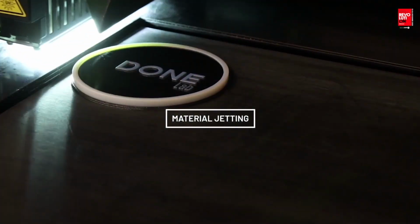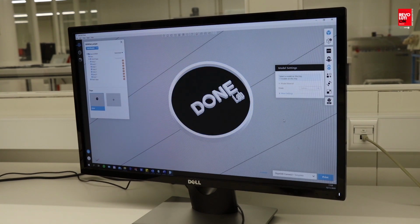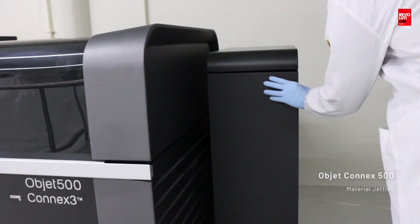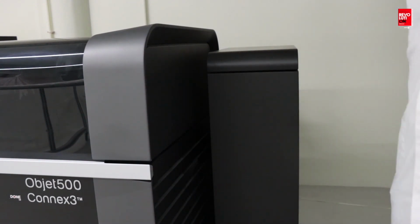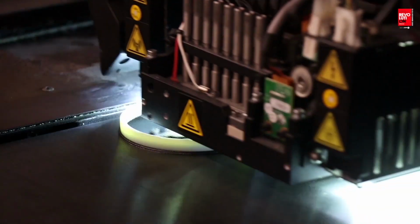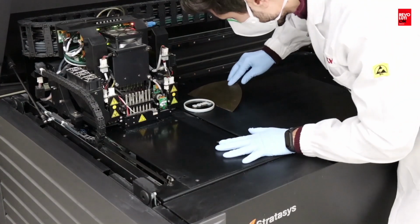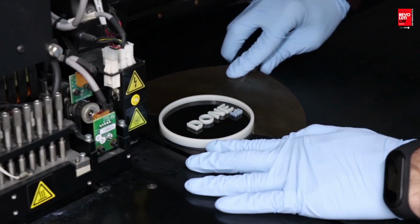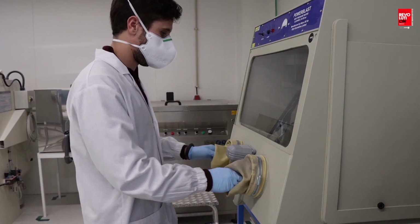Another technology that we have inside the DAN lab is material jetting. The material jetting uses a photosensitive polymer that cures with UV radiation. After we make the data preparation, we put the material inside the machine and this starts the production. In our machine, we have 2 lamps of UV radiation, and after the production, we can remove the part very easily from the machine. In order to remove the support material, we go to another station to clean with water, and after we finish the part.